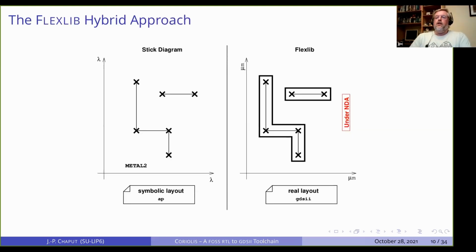So for our latest realization, we did use a hybrid approach with FlexLib. This approach was designed by Staf Verhaegen from Chips4Makers, and the idea was to keep, for example, the NSX-lib standard cell library block diagrams, and to map them precisely to the technology. This way, we can design the library once, and then directly map it to the technology.